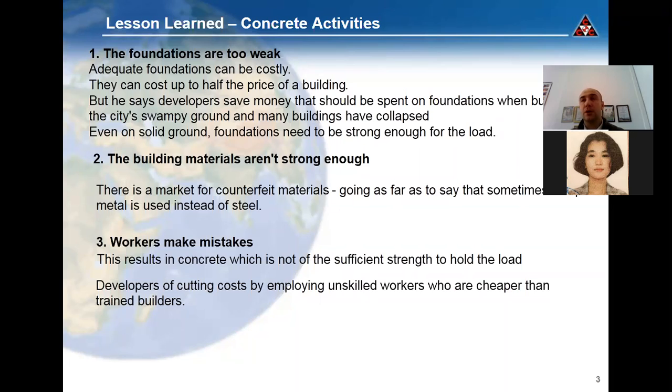Because designers who take part in accepting the type of foundation and size, and make the calculation of the foundation, first of all take into account the information about soil conditions. If there are no investigations about soils, it will be better not to take that project and begin to design it, because it will be a big mistake not to take into account the ground soil conditions.